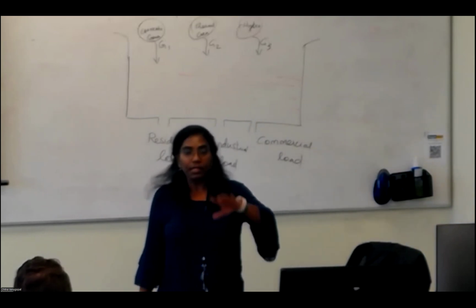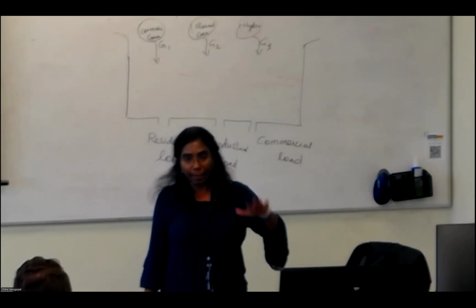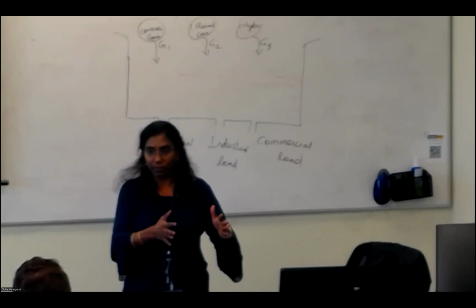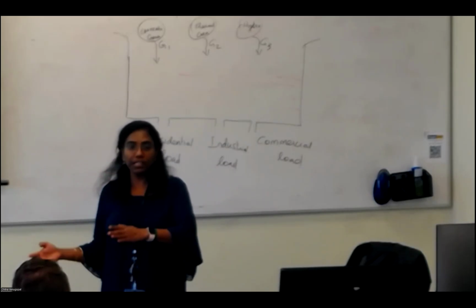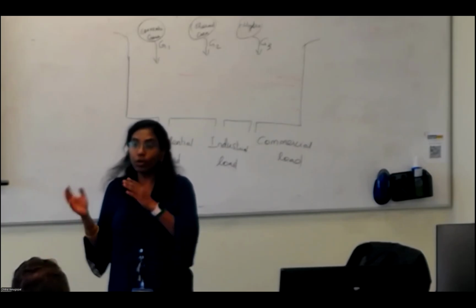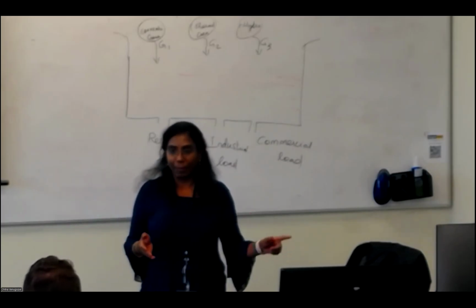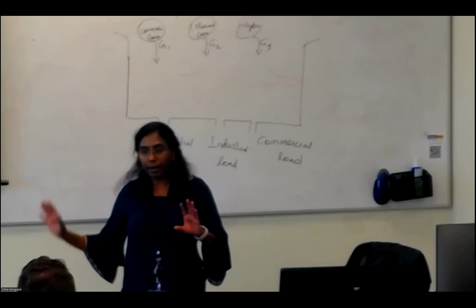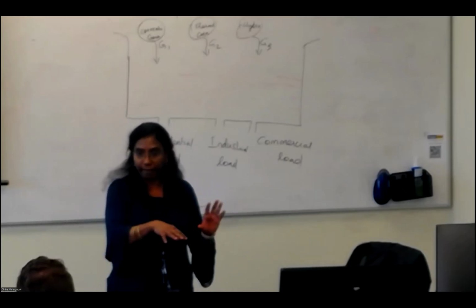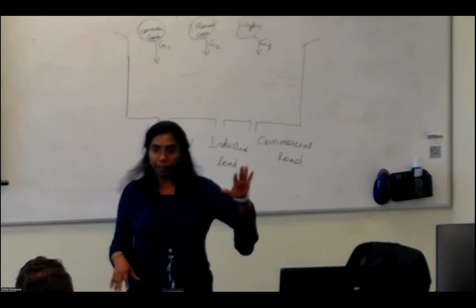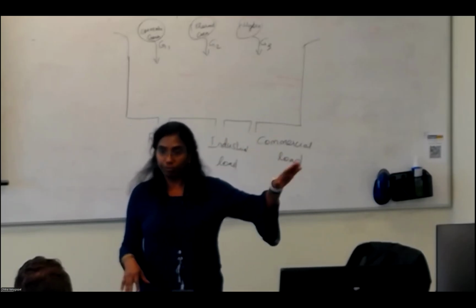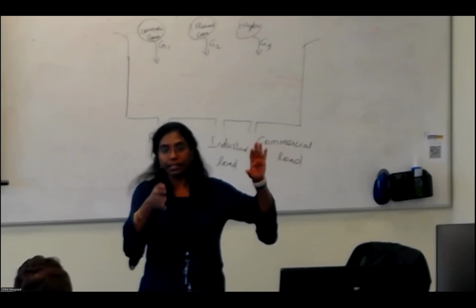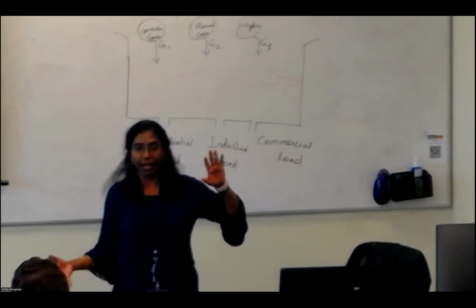Suppose, in terms of numbers, the generator capacity is 10 megawatts and I put the participation factor as 10, it is going to take only 10% of 10 megawatts and supply it to the grid. So whenever you add more loads to this diagram, even though the generator has full capacity to supply all the loads, if you put only 10%, then it is going to take only 10% from that.